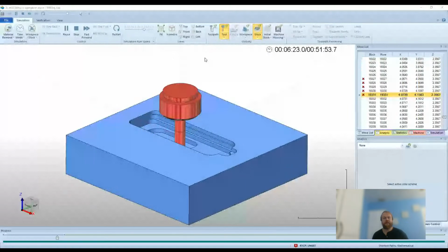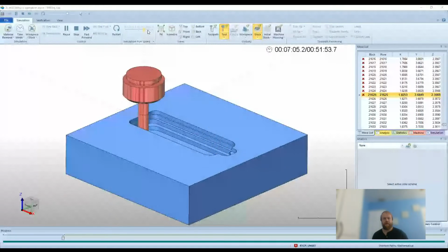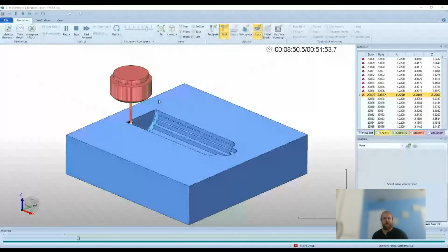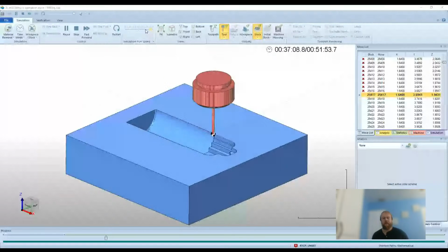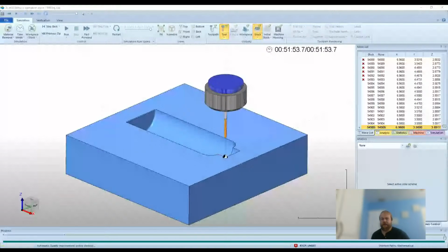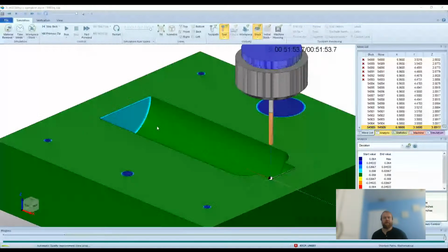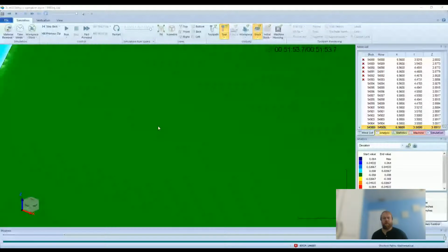So here's a roughing operation, then a planar toolpath with the 1/8" ball end mill. Once that's done, we'll go back to the deviation report. Again, I go to that analysis tab in green, the drop down is deviation, and hit refresh. Now I'm zooming in more and more. Everything here is in green.